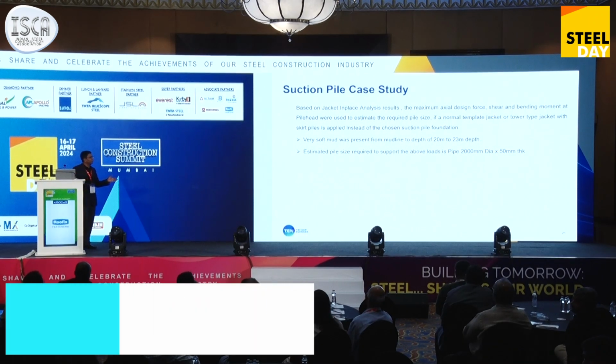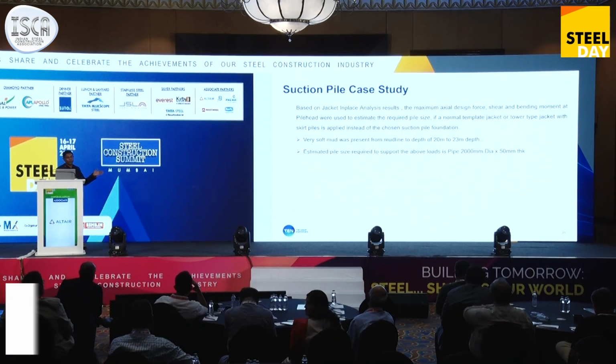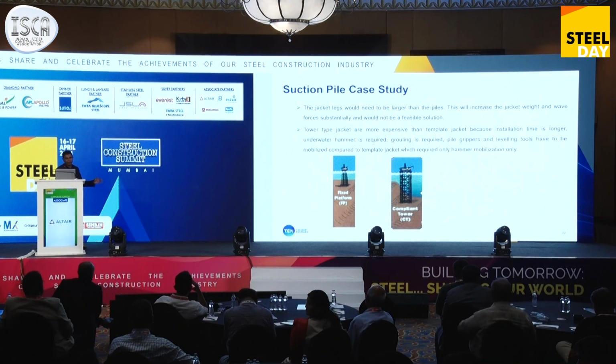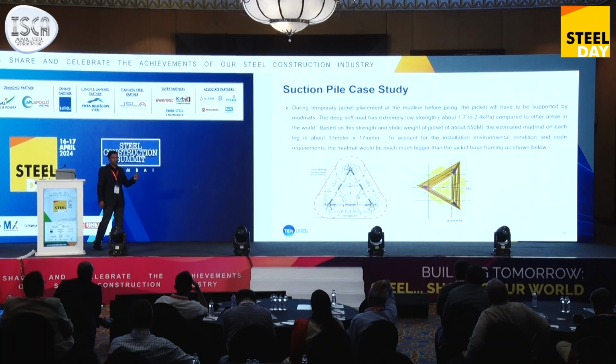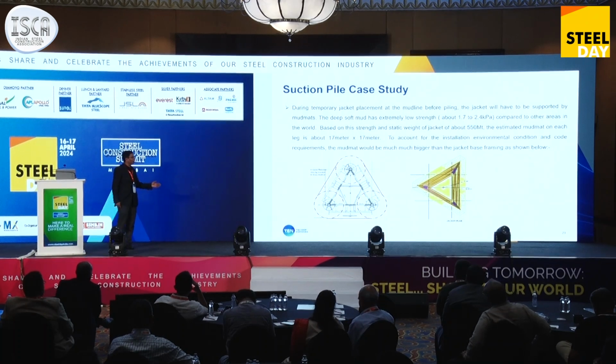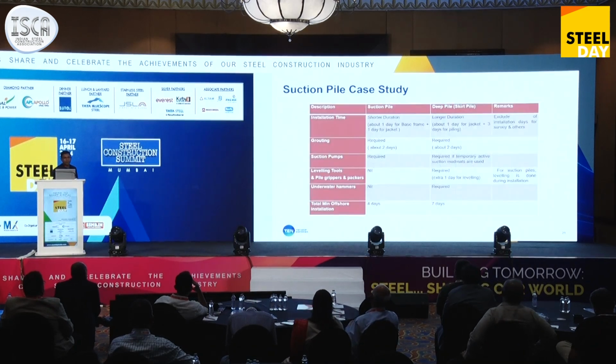The pile size, if you use the conventional, was very huge. So it was uneconomical. So we used the suction pile. And when offshore platforms are getting installed, you need a temporary foundation for the jacket. So that mud mat was also coming out to be very big. So then we chose this suction pile concept, and we did an installation study wherein we saved 3 days by using suction piles.